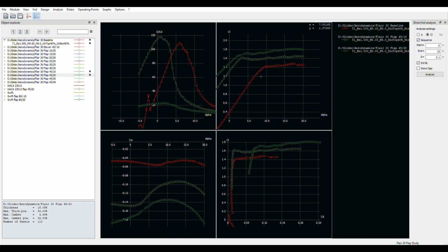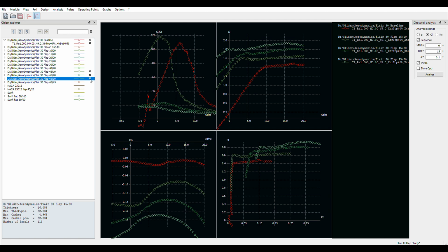And he decides, I am going to dump flap. I'm going to go 30 degrees. And he's here on the curve, and now his stall angle of attack is at 0 degrees, and he was at 7. So the glider is going to want to pitch as fast as it can from 7 degrees to 0 to get flying again.